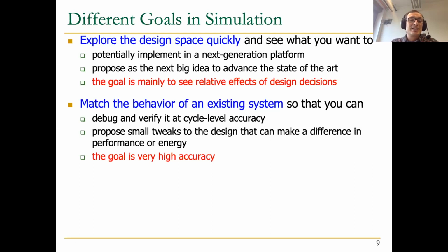I've seen many examples of this in real companies, for example, and usually RTL has an error bound of somewhere between 1 to 3% compared to real hardware that is supposed to implement that RTL. So what do people do? After they get the hardware, they go back to the RTL and they try to match the behavior of the existing hardware to the RTL simulation. And they actually improve the RTL at the same time that way. And they also figure out why the real hardware didn't match the RTL. And usually the answer is someone who's custom designing the logic took some shortcuts to minimize area, whatever reason they had, that made the behavior of the actual hardware implementation different from the RTL itself.